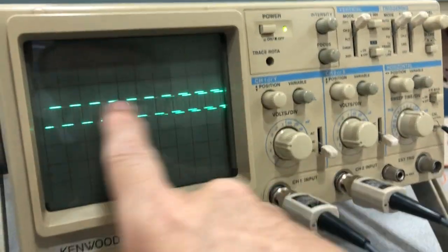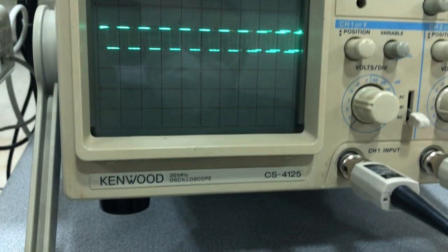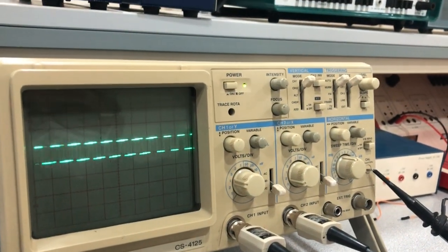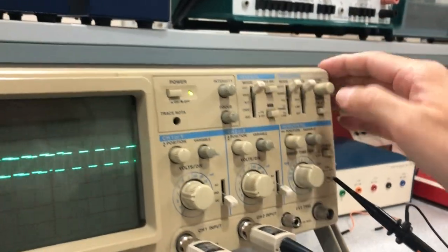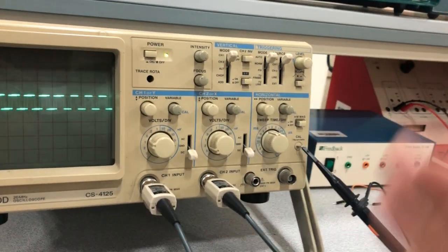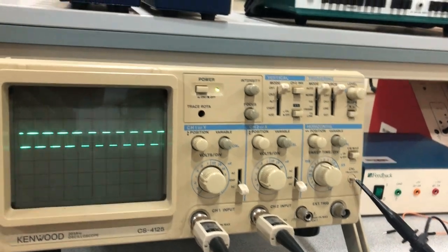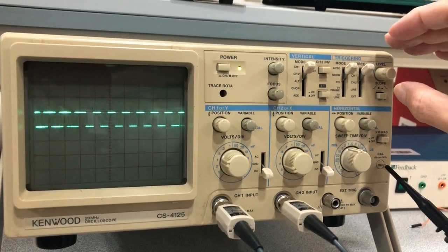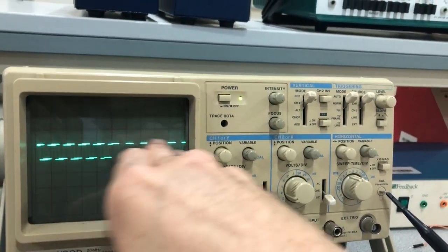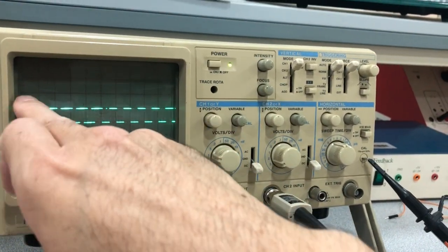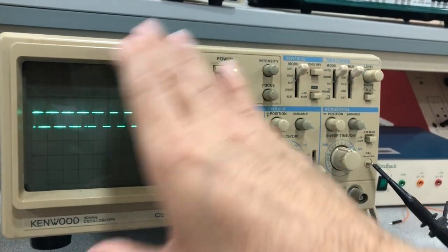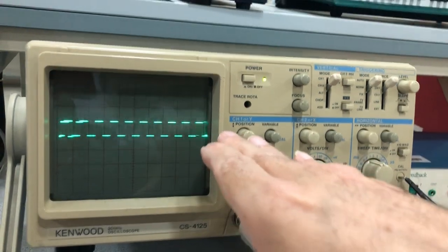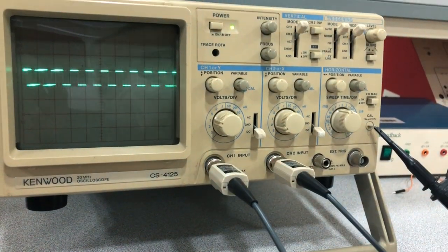Now I notice that my signal is horizontally scrolling to the left. It's not stable. So now we have to talk about something that confuses most people. Okay, it's called triggering. The scope has to start plotting at a point of your signal. Imagine the triggering: you have a horizontal line here. It's called the triggering level. It's a horizontal line, but in all these scopes, it wouldn't show it to us. We have to imagine it as a horizontal line, and there's going to be a crossing between it and our signal.